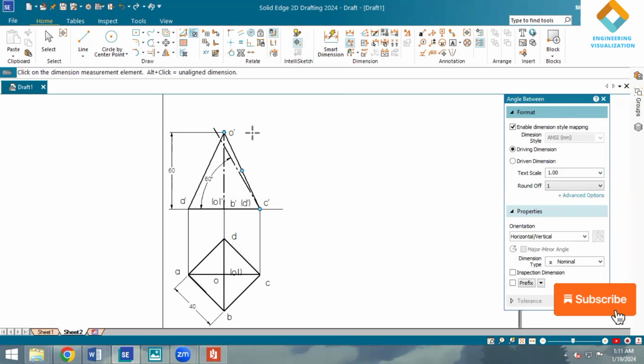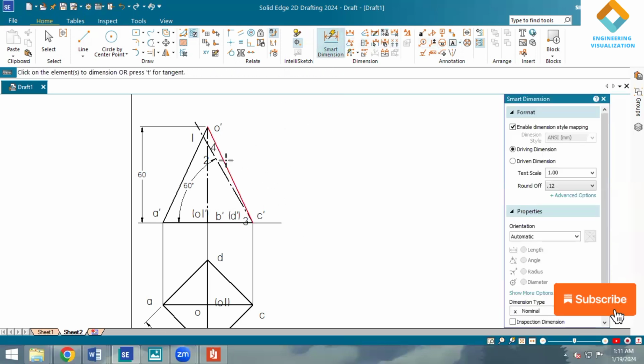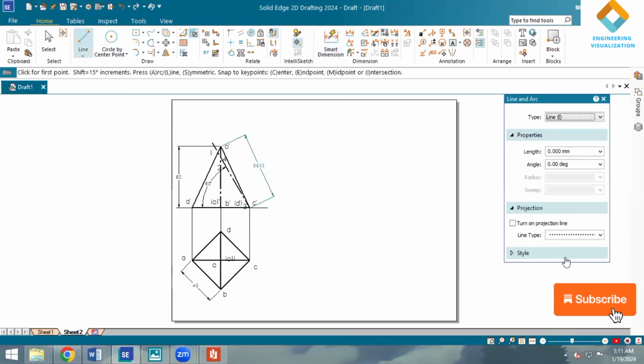Now we have to mark the cut points here. The cut points will be marked with numerals. Cut point 1 is cutting on the slant edge AO, and 2 is cutting on the slant edge BO. Cut point 3 occurs at the extreme corner C, and 4 is cutting at DO, the slant edge. So the cut points are mentioned. The slant edge CO is parallel to XY, so there is no need to find an extra slant edge, it is already available.